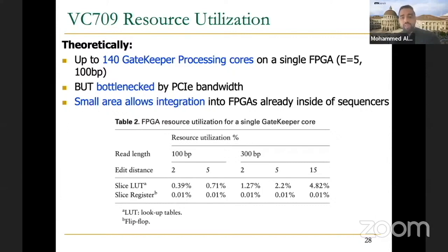You may want to pipeline these problems together because the maximum delay you can have cannot achieve the maximum frequency you can use in the FPGA. So the critical path in FPGA implementation is very important here, so that you can drive a lot of these gates in parallel. Sometimes you cannot apply the VCC or the ground to a large number of gates, and that's specified or controlled by the total critical path or the worst delay in any of the input signals, for example. So you may need to use pipelining techniques to reduce this critical path, or you reduce the number of replications. These are all challenges when you implement a parallelized algorithm in FPGA, or you would like to fully utilize all resources you have in the FPGA.